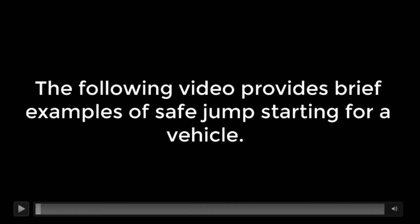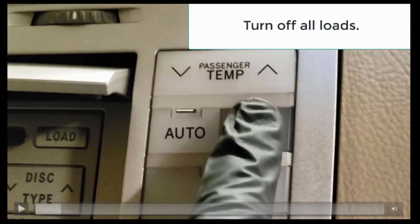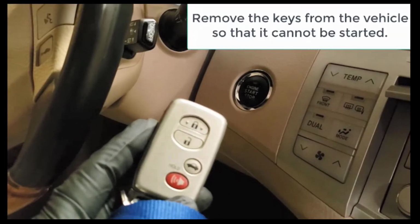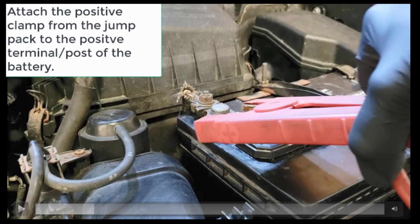So in this example, what you want to do is start by turning off loads. We want to turn off as many loads inside the vehicle as possible. We don't want to have anything on. The other thing we want to do is disconnect plugs from any outlets. We don't want to have anything plugged in, like phone chargers or radar detectors or anything else. You also want to remove the keys from the vehicle so that it can't be started. Here, we're going to attach the positive clip from my jump pack first.